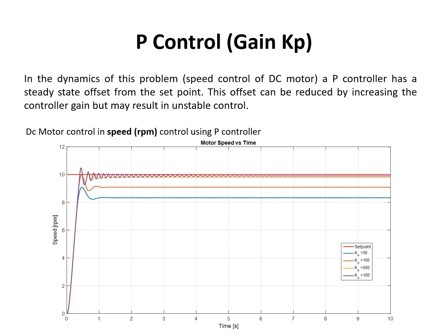And here we can see this. Again, as we increase Kp, we see the error term decreases. However, at a very high gain, we see some oscillatory nature popping up in our system. And again, this is not ideal to have. Okay, so while we can drive the error down simply by increasing the proportional gain, it does mean the stability of the system, or the overshoot and response of the system, might be slightly affected by that.